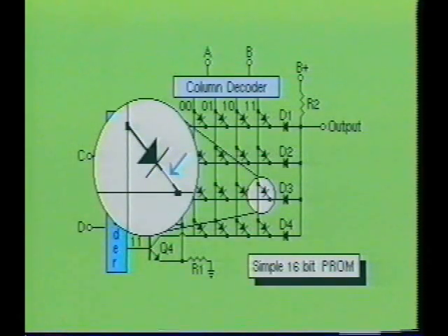Another difference is that during the construction of the PROM device, each connecting diode contained within the memory array will have a thinner layer of conducting material attached to it. This thin layer acts as a fuse link, which will open to produce a low state when the device is programmed.